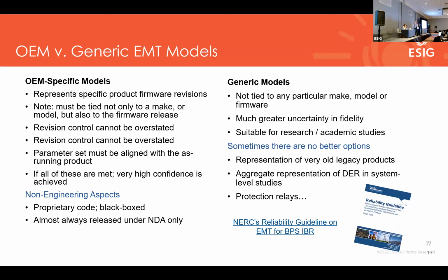These products are getting better and more capable, but you have to make sure that you're mapping to the firmware, because you could have two different makes of inverters that look the same, but the performance is software defined and can be very different. So we want to tie that to not only the make and the model, but the firmware release. Revision control cannot be overstated.